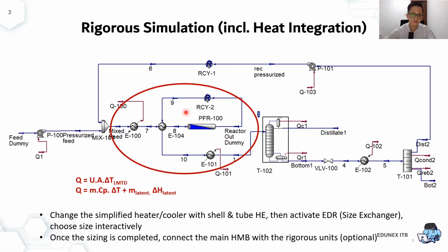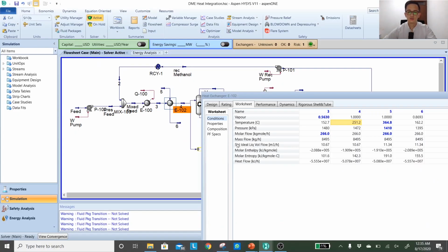my slide. Imagine Q equal to U multiplied by A multiplied by delta T. So the A will be fixed, and the U is roughly going to be fixed. So what needs to happen now if we have the same amount of A but we want to get to a smaller temperature? Likely we have to change the feed condition of the heat exchanger. So we have to change the vapor fraction, and you have to imagine what would happen if you decrease the vapor fraction.